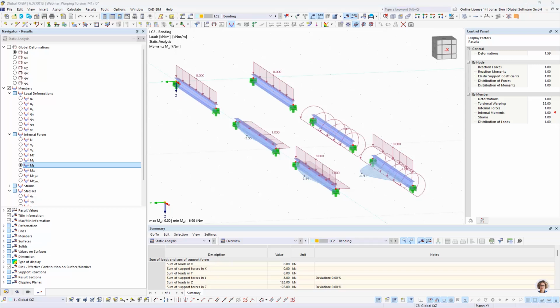All right, so this leaves us with 2 examples done. For the remaining time, I would like to focus on some additional peculiarities that need to be considered when setting up a 7 degrees of freedom calculation in RFEM and RSTAB. Until here, we have learned how to activate the 7th degree of freedom, how to apply boundary conditions and stiffness or discrete warping restraints along a member length, and also how to assess the results for warping torsion.